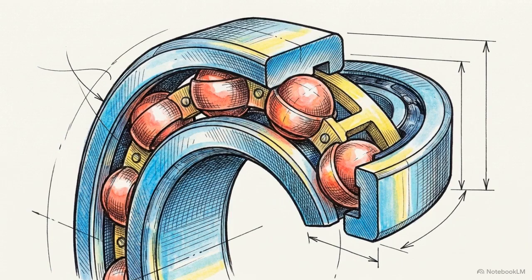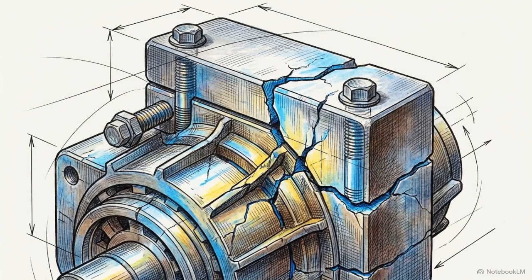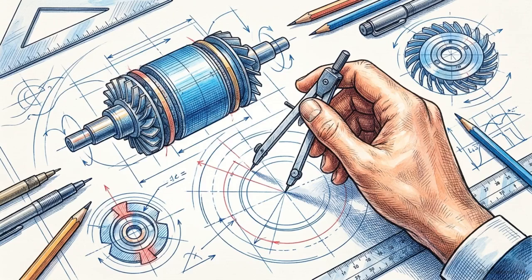The microscopic offset generates violent, unbalanced centrifugal forces that warp the machinery. These outward forces rapidly increase the loads on the internal bearings. Over time, this repetitive stress threatens the structural integrity of the entire chassis and produces dangerous, escalating vibrations. Simply adding thicker steel to the casing cannot solve the problem. To keep the machine from tearing itself apart, engineers must actively calculate and zero out the unbalanced forces.